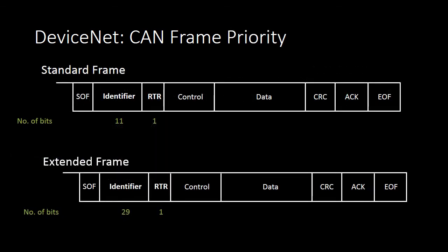There is also an extended data frame type with a 29-bit identifier field, and the devices will need to be configured to accept the correct size frame. Devices that only accept standard frames will not accept extended frames, and devices that accept extended frames will also accept standard frames.